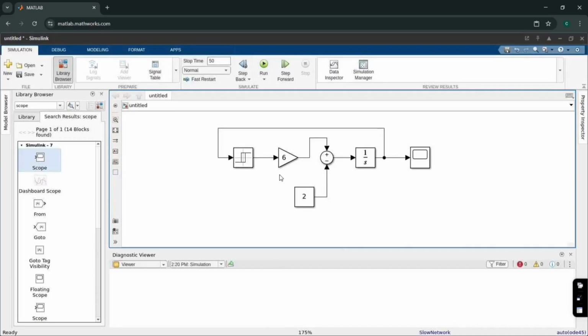The main objective of this system is to automatically monitor the soil moisture level and activate watering only when necessary, ensuring that plants receive the right amount of water while minimizing water waste. The system is designed as a closed-loop control system, meaning it continuously checks the condition of the soil, compares it with a desired value, and makes decisions based on that comparison without requiring manual intervention.